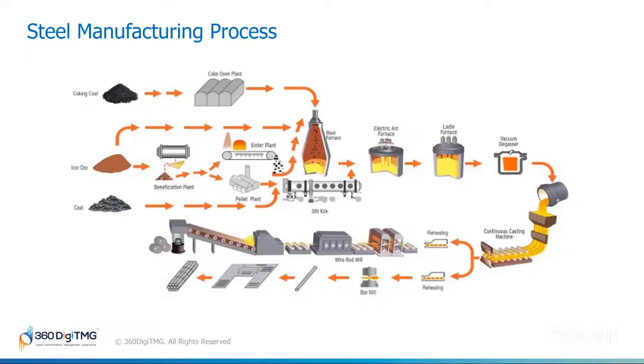The chemical analysis of the steel happens in the electric arc furnace, where we check and adjust elements like carbon and silicon to ensure the steel is the right type. Once melted, the steel moves to the ladle furnace for small adjustments like chemical composition, to get the right steel grades. After that, the steel goes through the vacuum degasser, which removes any unwanted dissolved gases trapped inside the steel. Finally, the steel is poured into a mold to cool down into slabs or shapes like billets. These are then processed in the rolling mills to create steel grades. Grades means different types of steel products.